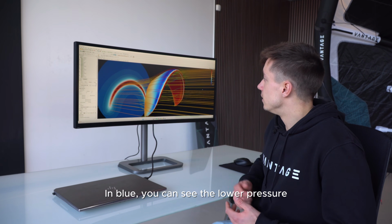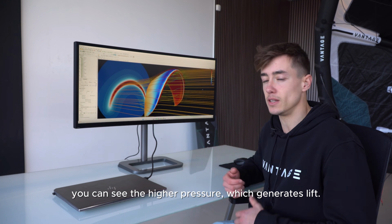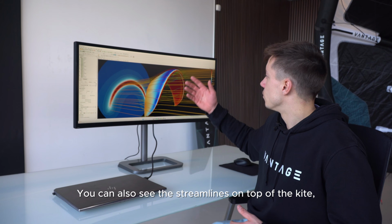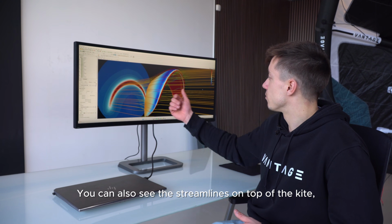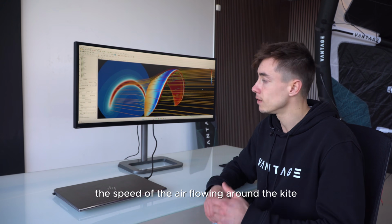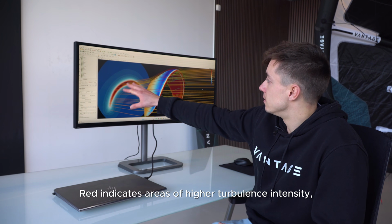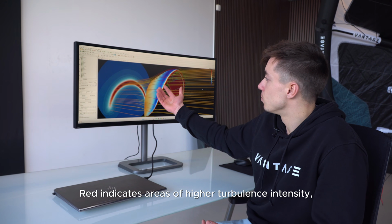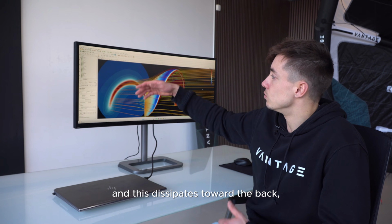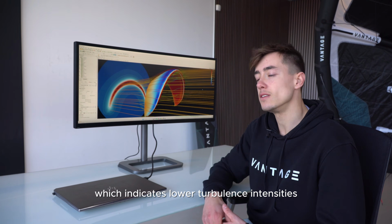In blue, you can see the lower pressure, and in red, on the underside, you can see the higher pressure, and this generates lift. You can also see the streamlines on top of the kite, and this indicates the speed of the air flowing around the kite. In the back, you can see the turbulence intensity, and in red, this indicates higher turbulence intensity, and this dissipates to the back, in blue, which indicates lower turbulence intensities.